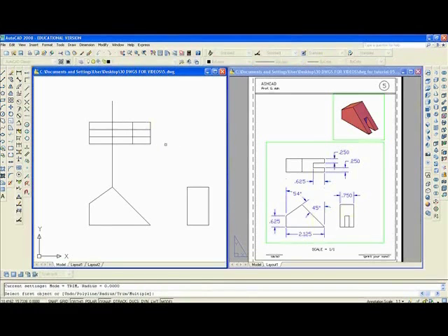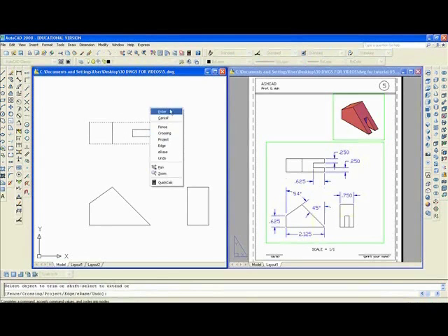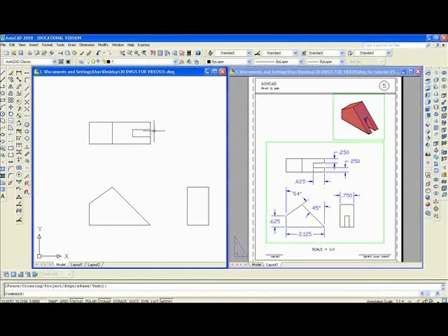Escape, F enter for fillet, and clean up the intersection, clean up that intersection. We also want to trim, TR enter. Trim from that line and that line, enter these two lines. This has to be empty.